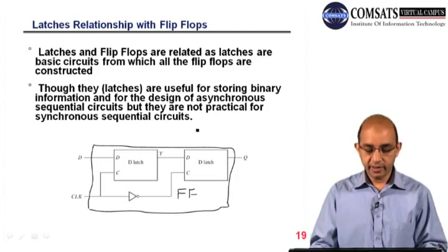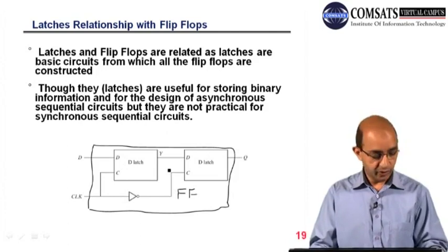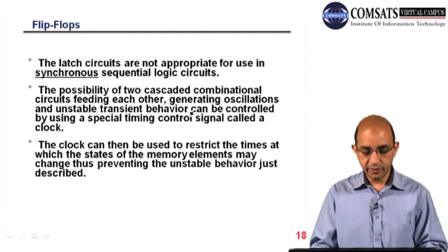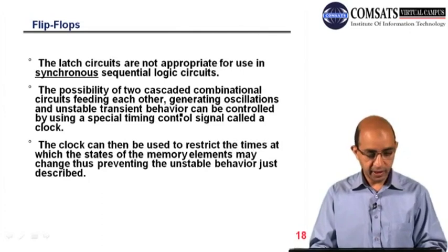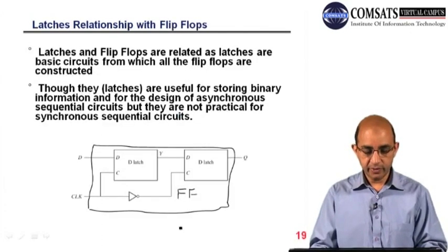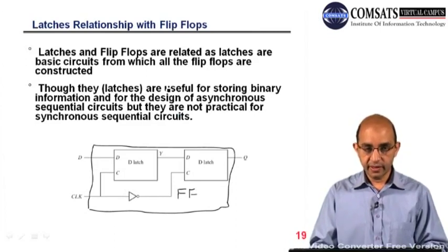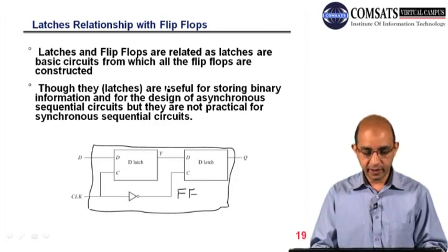As a result of this cascading, we are able to resolve that sort of problem: the generation of oscillations and transients, we are able to control by cascading two latches. So there is a relationship between latches and flip-flops: the latches are the basic building block for flip-flops.